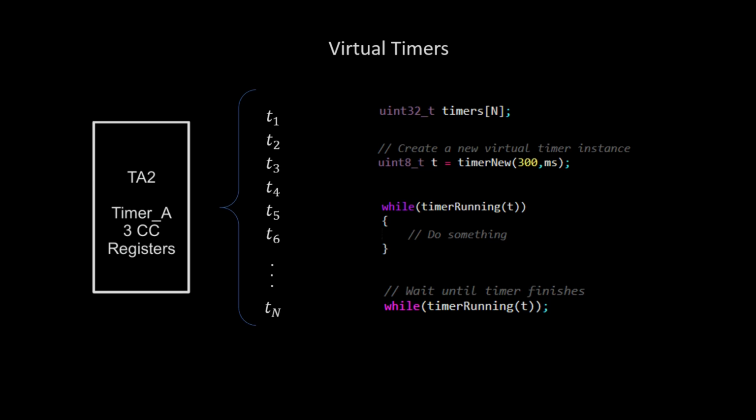If we want to use a blocking mechanism, I can also do it with this formalism. I can use a while the timer is running, don't do anything. So I use a semicolon here at the end to block the execution until the timer finishes counting. So this is an interesting idea that I work with a lot in my projects.